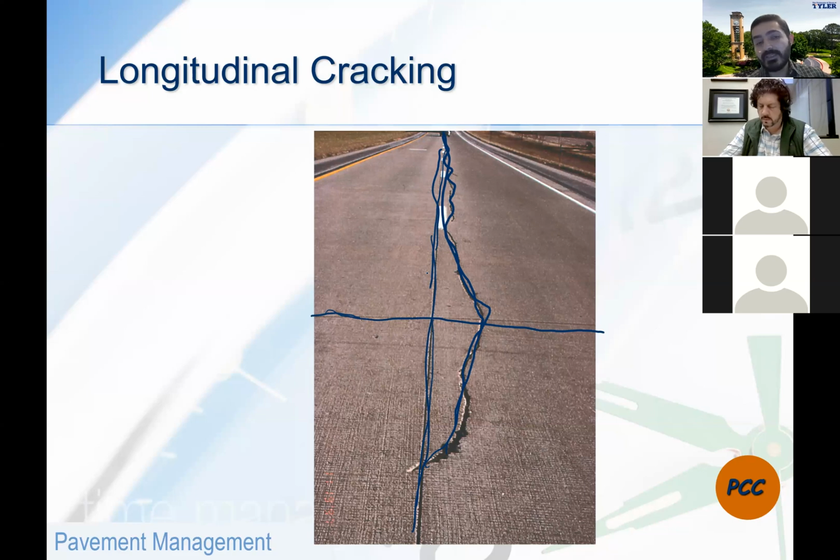If it's a low severity longitudinal crack, typically we seal it. If it's high severity, we're going to end up with removing again the whole piece and reconstructing it again.